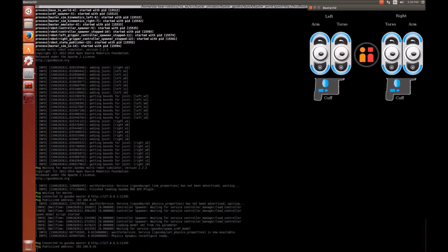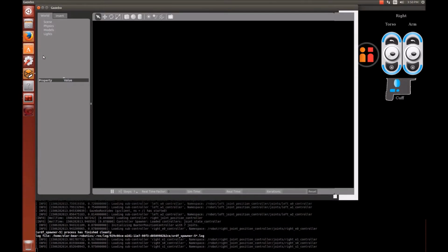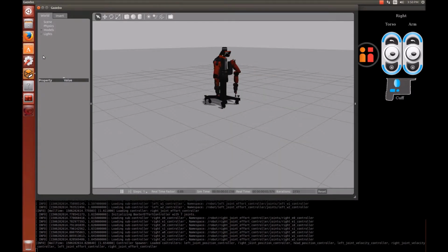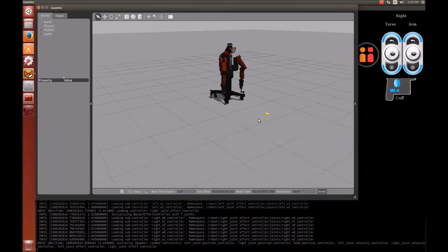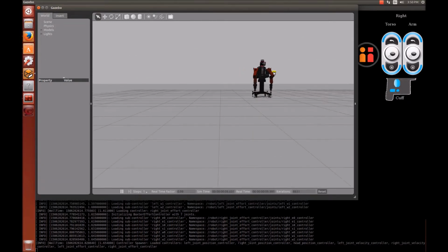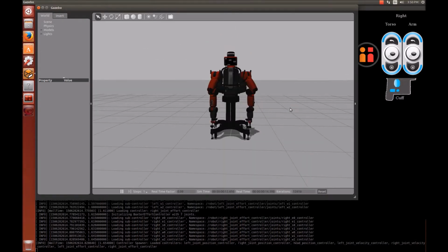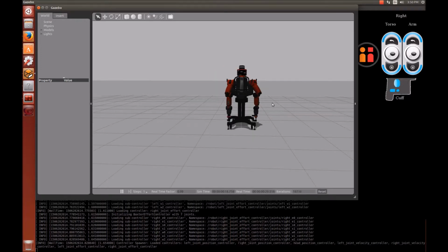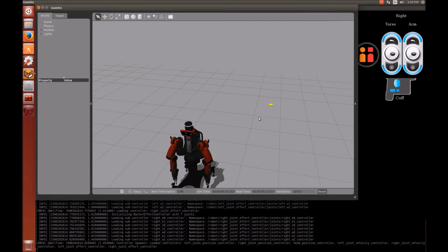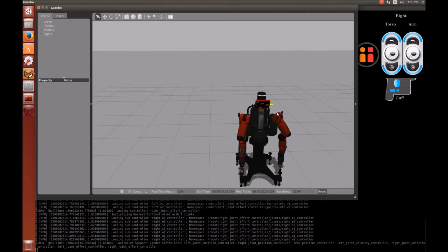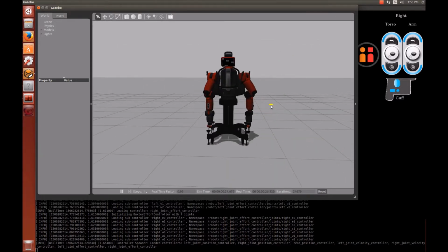The Baxter robot was simulated using Gazebo running on ROS Indigo. This simulator was developed by Rethink Robotics and is part of the Baxter software development kit. This software development kit, along with the Baxter Robot Raconteur bridge, was used to create a service that allowed MATLAB to send the Baxter the change in workspace positions from the Phantom Omni, and then those change in workspace positions were translated to the corresponding joint angles using the software development kit's inverse kinematics service.